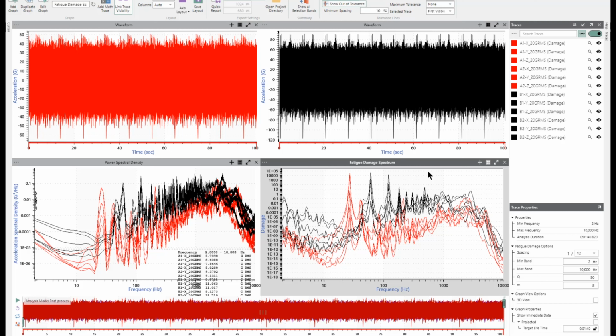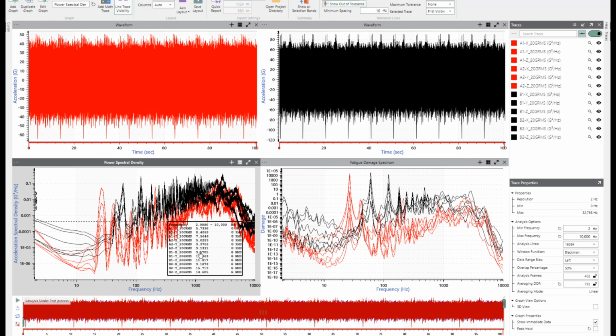Now, we have some damage properties down here, our octave spacing, the frequency range that we're analyzing, our M and Q, and those are the values that we're using to calculate the relative damage, assuming there's a resonance at each one of these, what turns into a single degree of freedom oscillator or a very narrow band frequency.